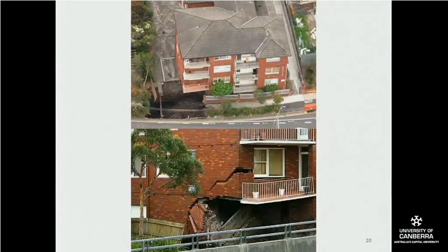So what's good about brick? Brick is really good in compression. It's very long-lasting. Lots of ancient examples still exist today. It's a very low-maintenance material, and it's got a particular way of failing structurally, which is quite fascinating, where basically it will fail along the mortar lines, and one brick will transfer the load to the next brick if you've got a stretcher bond, a normally overlapped way of laying bricks like you see on this wall here. So what happens is you can remove the whole corner of a building, and the building will remain standing.